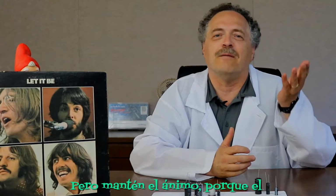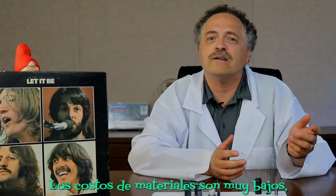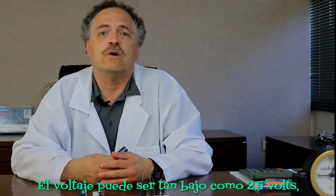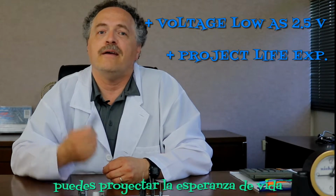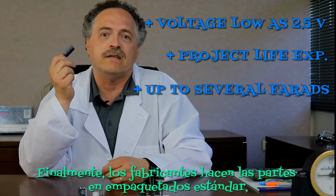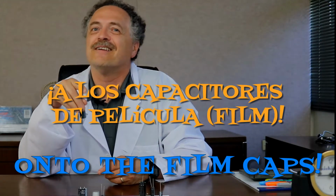But keep your chin up, because cost, size, availability are all on your side. The material costs are very low, parts are the smallest, and multiple suppliers carry them. The voltage can go as low as 2.5 volts. You can project their life expectancy, and they can have large capacitances reaching several farads in a single container. Finally, vendors make the parts in standardized case sizes, which makes your life a lot easier.